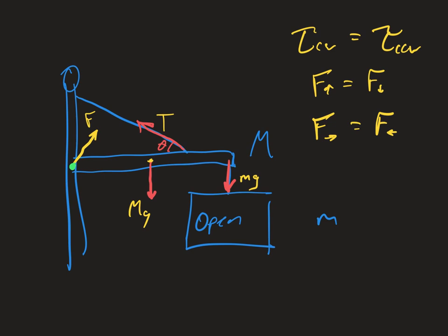So instead, when I'm doing my net torque calculations, here I'm going to erase that to make a little bit of space. My clockwise torque would come from the weight of the pole and the weight of the sign. So tau pole plus tau sign would equal the counterclockwise torque, which would be tau from the tension. In the case of the downward forces, they both make a 90-degree angle, so the sine terms just drop off. They become 1. Sine of 90 degrees is 1.